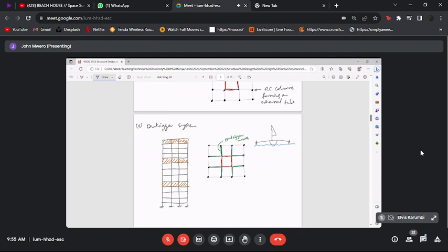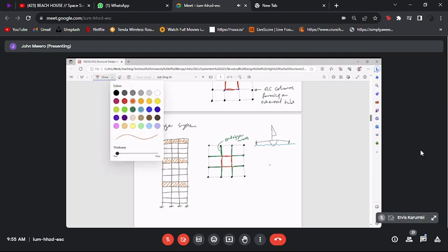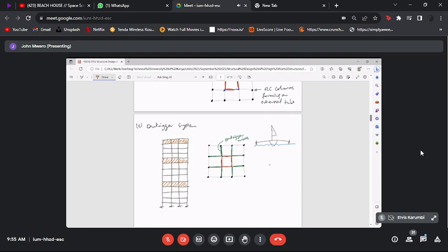So this building, when it wants to sway, the very deep elements, which are walls basically, that are connecting the central core to the external columns, sort of stabilize the building, so they reduce the sway significantly. Okay, so that is called an outrigger system. Usually what happens is that you would put this system in the floors that are referred to as service floors. So these would be service floors.